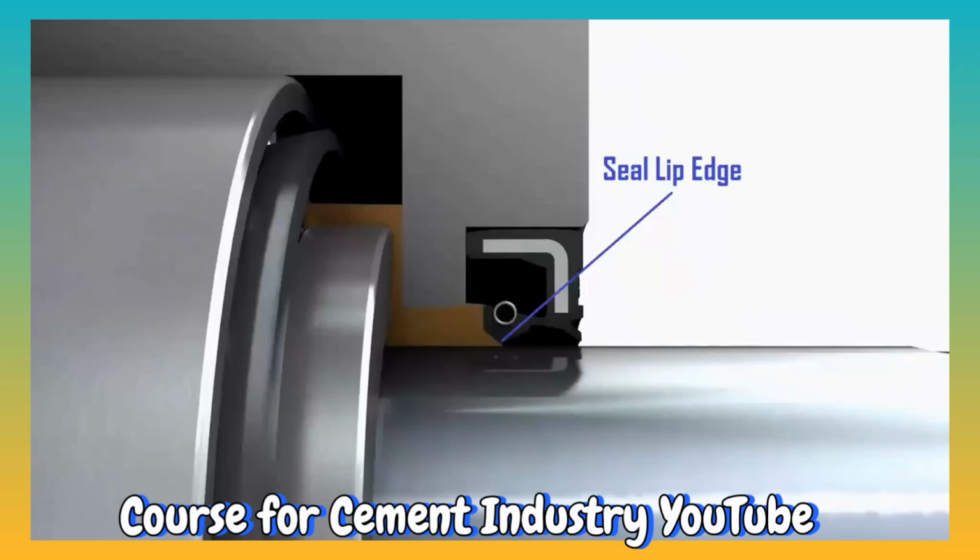The seal lip edge is the part of the seal that holds the fluid or lubricant in the engine from leaking out through the gap between the shaft and the engine housing. At the top of the seal lip edge there is a garter spring, which is a spring that extends in the form of a ring around it. The function of the garter spring is to press the seal lip edge so that it always presses firmly on the shaft so that there is no gap that allows lubricant or fluid to leak out.